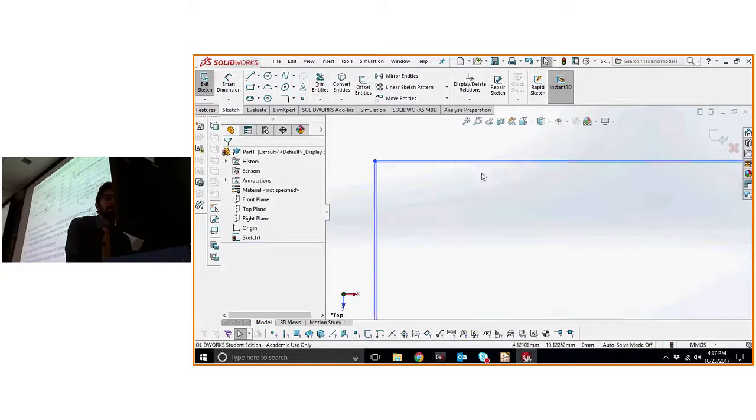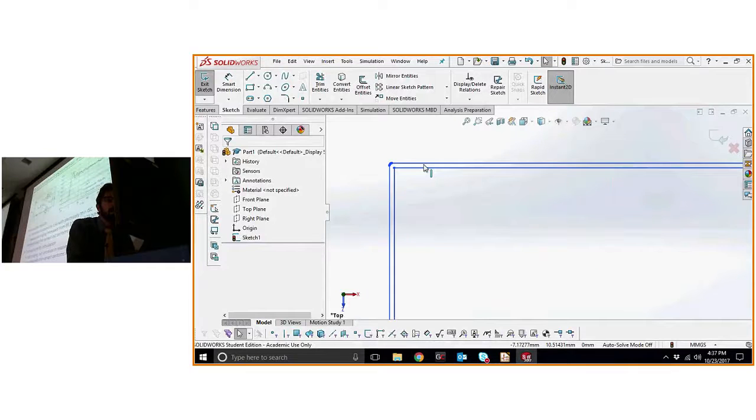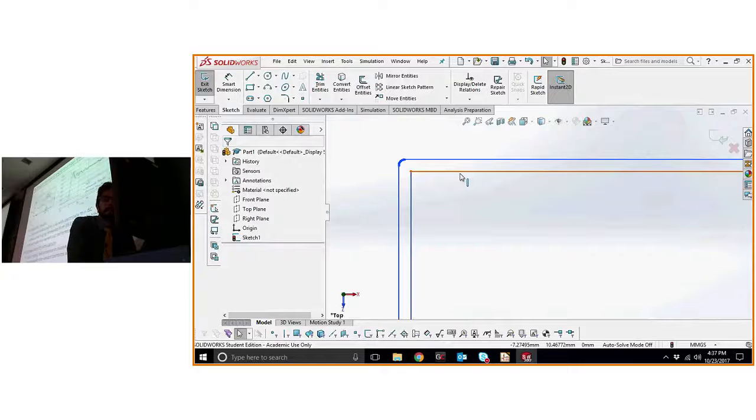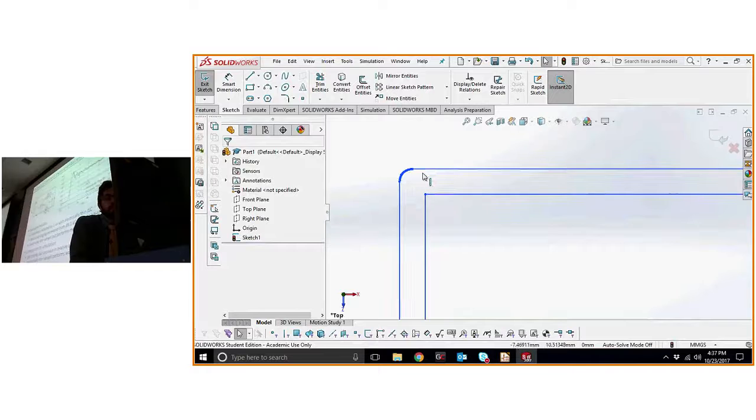Now the thing is, whenever you get any sort of output from your PCB design program, it outputs traces. Depending on how it exports them, the board outlines a certain thickness line in KiCad, and in this case, SolidWorks interpreted that as a shape instead of just a line.